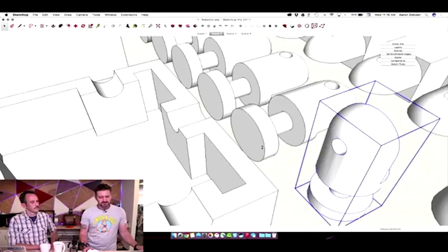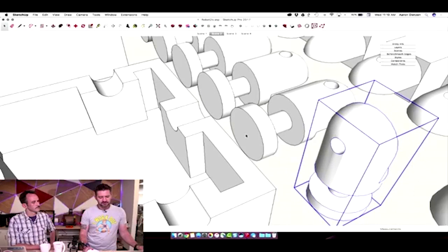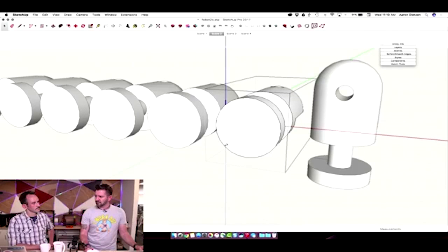Laying down specifically, I had a problem printing this circle vertically. So I had the same problem. Printing a circle on end like this ends up creating some ugly geometry on the bottom half. Top half stacks up great, but because of the way that the slices are going across, I ended up with some bunching and some overhangs. It just didn't look good.